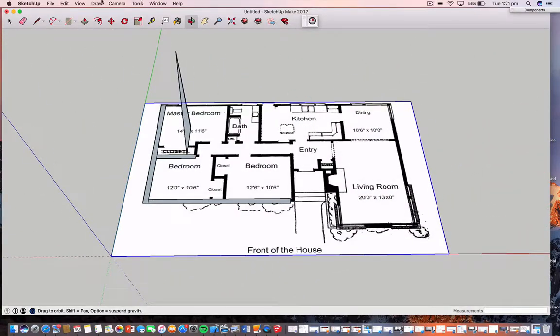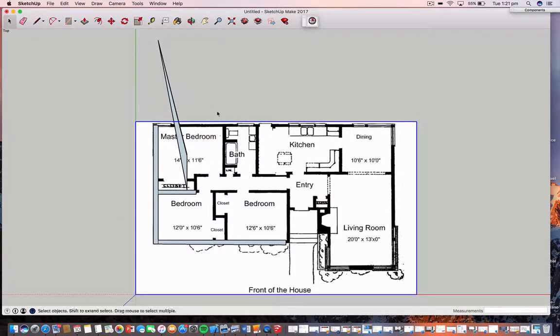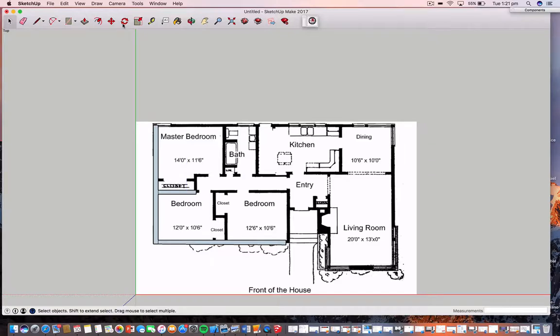So what we do, let's just go back to the top camera view, that means it's the best chance you've got. Delete those, just click on them and hit delete, they disappear. And that's where sometimes using that rectangular tool means that you're definitely getting a closed face for your wall, which is exactly what you want to be doing.